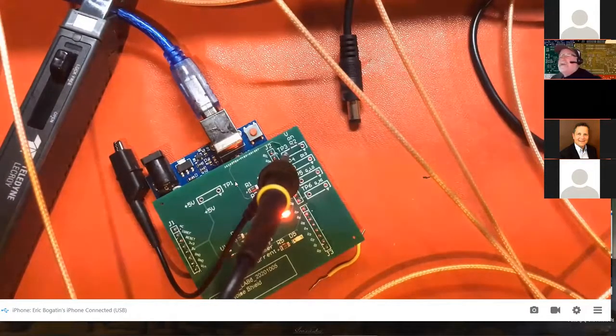And so if the probe bandwidth is 500 megahertz, do you need 2 gigahertz bandwidth in the scope? No, but you need a gigahertz bandwidth, and that's using the 10x probe. I showed a couple of examples here of the differential probe and the REL probe. The REL probe bandwidth is 4 gigahertz, and so if you're looking at fast transient noise, switching noise on the power rail, having the highest bandwidth you can afford in the scope will let you, again, open up that window into what's going on that may reveal to you some hidden noise issues.